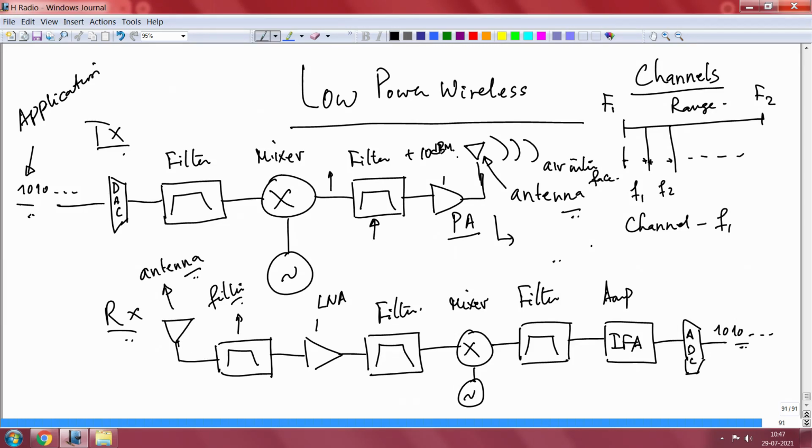Only then you can actually see whether you are getting the signal decoded properly or not. Now if you are not able to decode properly, you may have a problem anywhere here, because there may be too much noise up to this point, or there may be a problem that the distance between the transmitter, the TX, and the RX is large.